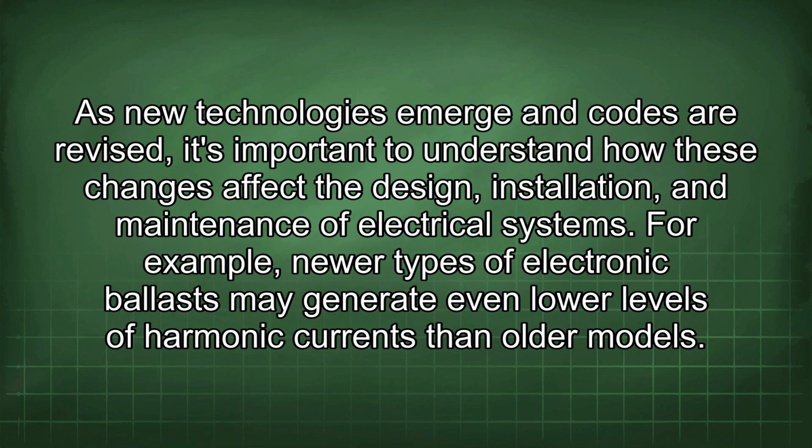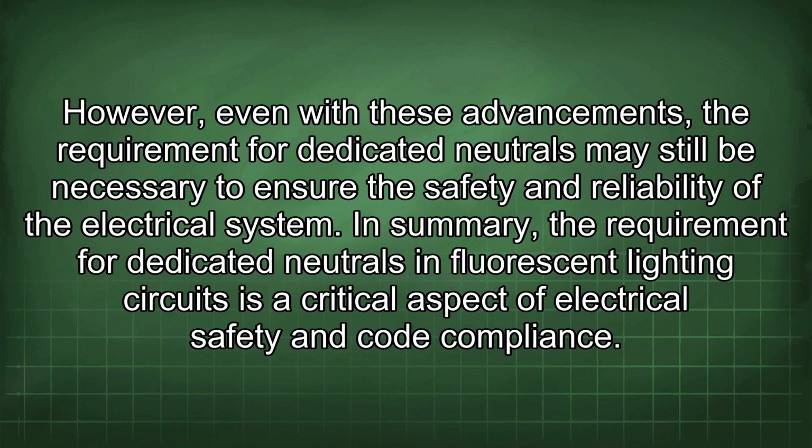As new technologies emerge and codes are revised, it's important to understand how these changes affect the design, installation, and maintenance of electrical systems. For example, newer types of electronic ballast may generate even lower levels of harmonic currents than older models. However, even with these advancements, the requirement for dedicated neutrals may still be necessary to ensure the safety and reliability of the electrical system.